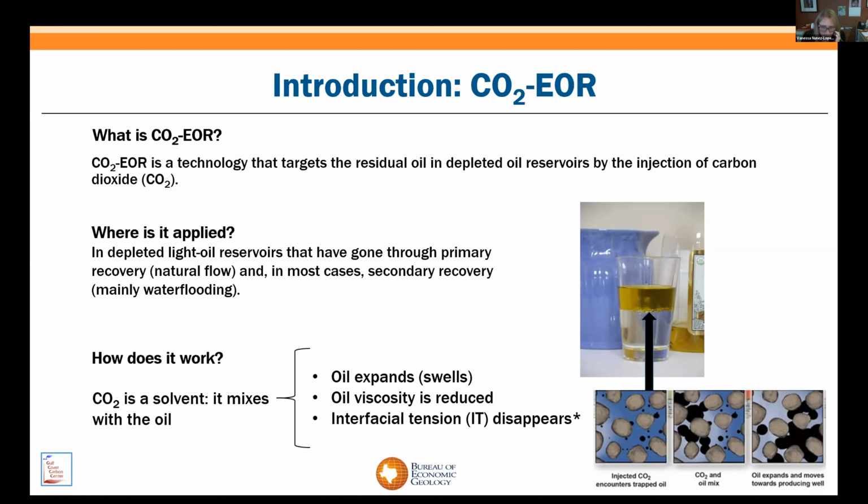So CO2-EOR is an advanced oil recovery technology, right? It's usually applied after water flooding, at least here in the US, to extend the economic life of depleted oil fields. So when that is the case, the technology targets the residual oil that was left behind by water flooding by injection of CO2. When CO2 is introduced into the reservoir, several physical mechanisms enhance oil production.